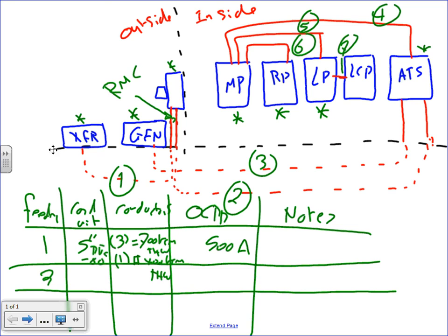Or actually, PVC Schedule 80 is rated. I would use for this part PVC Schedule 80 because it's rated for physical damage. Anything above, all the stuff above is EMT. Anything here is PVC. Does that make sense? Schedule 80. So 2 conduits I suggest to use PVC Schedule 80. Anything inside or outside, underground or outside, PVC Schedule 80. Anything inside the building, EMT.